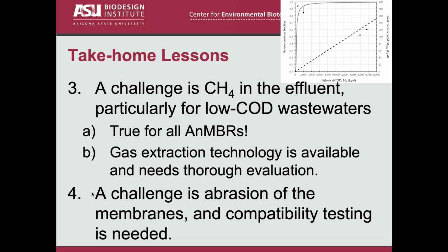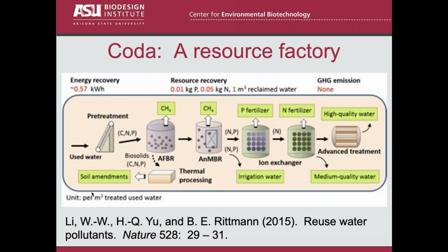So I'm almost to the end, but I'm going to give you just a short coda here. A few years ago, with some colleagues in China, I published a paper in Nature about what we called the resource factory. It's basically capturing all the value out of wastewater, in this case of this domestic wastewater. And you can see the diagram here that after screening, you've got the two stages of the anaerobic MBR, generating methane. And then we also evaluated recovering the nitrogen and the phosphorus and producing really high quality water.